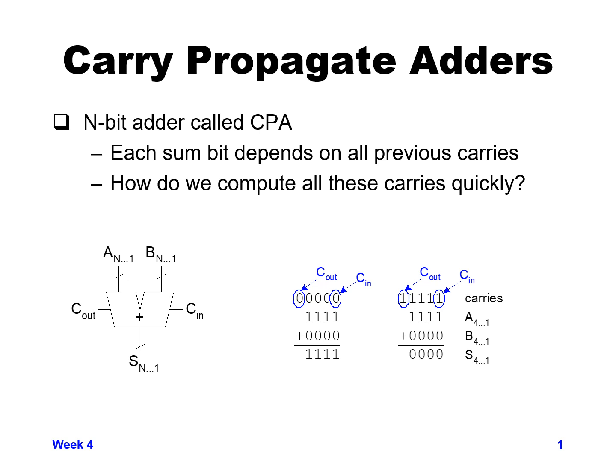If we have an n-bit adder, called a carry propagate adder, we have an A input with n bits, and a B input with n bits. We want to add A and B together with a carry in, and generate a sum of n bits and a carry out.